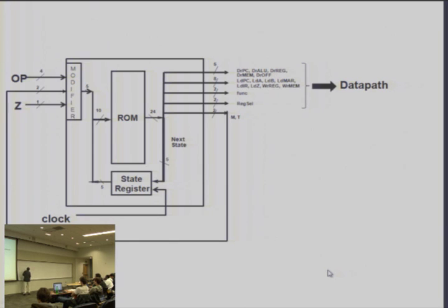So as a bunch of gates like this, and this is the output that you want to generate, and you have as many of these AND terms as the number of individual terms that you see in this equation, and the number of OR inputs is the number of things that you are ORing together in order to generate this particular logic function.